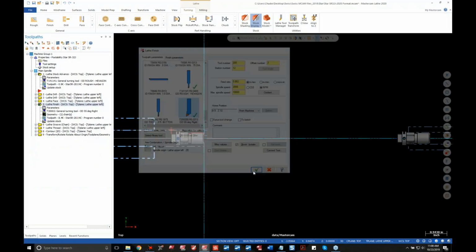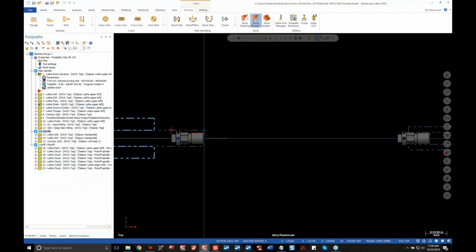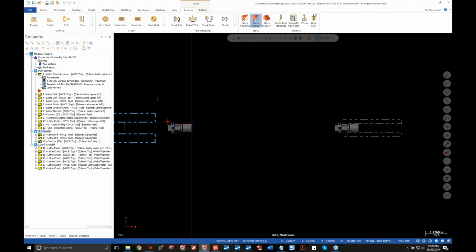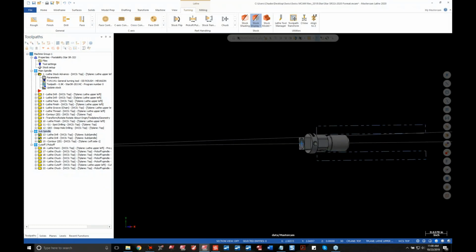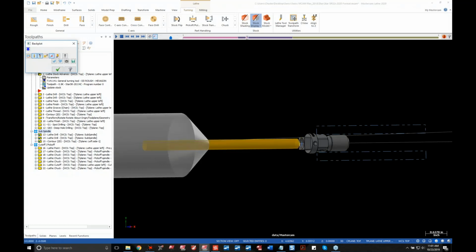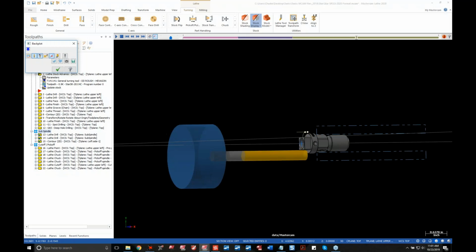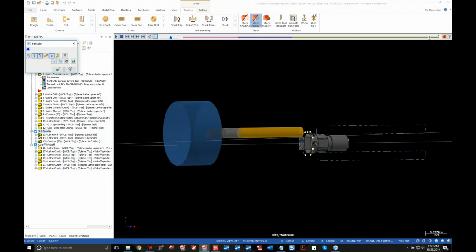So the sync is available if you need it in there. Okay. The sub spindle ops are right down here. We'll zoom in so you can see that. These are all programmed with the right axis combination, so it's coming out on the sub. It's doing a chamfer, a spot drill, a regular drill, and then it's milling the flats around the OD right there.